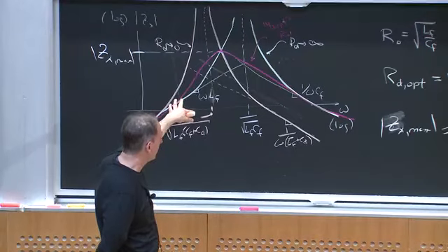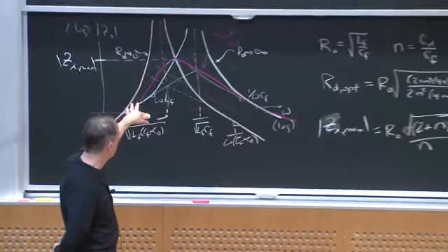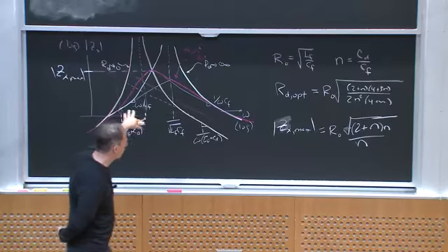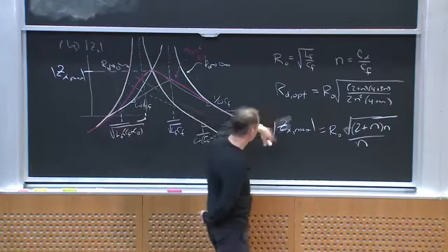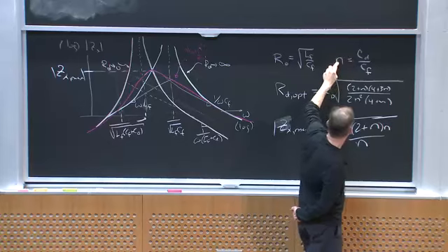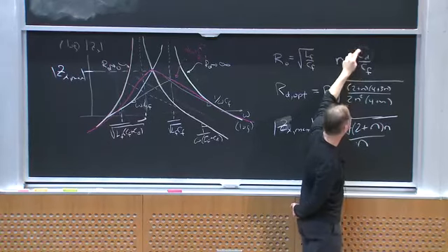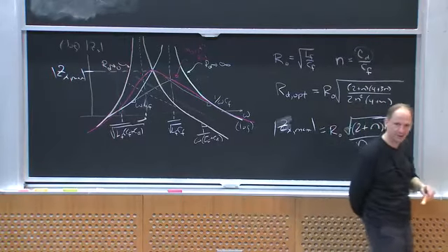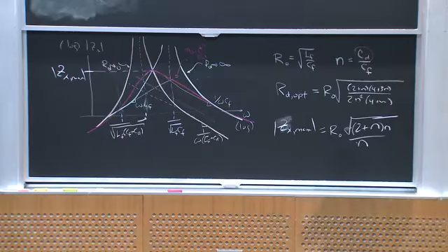The nice thing about this is that you can say, well, how well damped do I want this thing? I will pick n big enough to give me that, and then that gives me my value of damping capacitor, and away I go, and I can make my output impedance small or my system well damped.